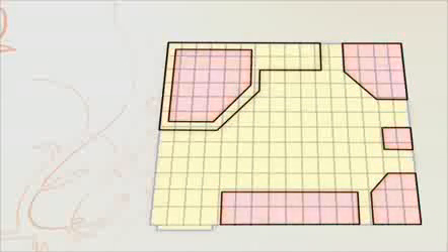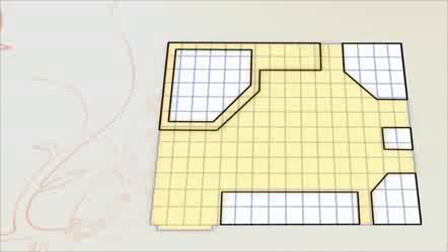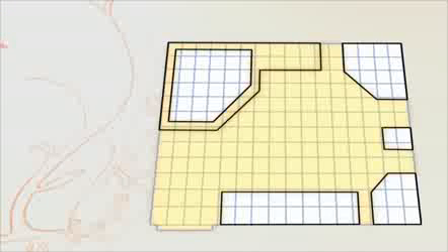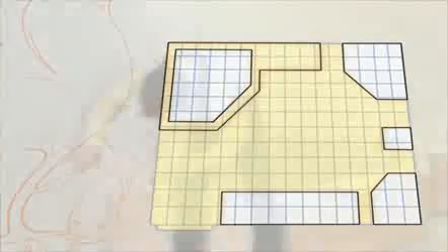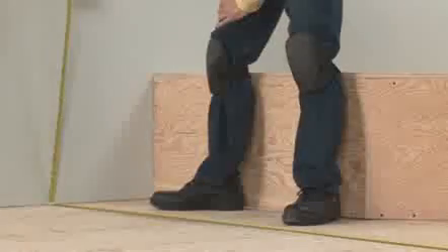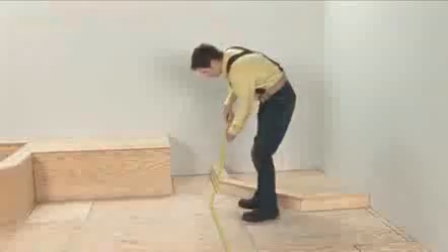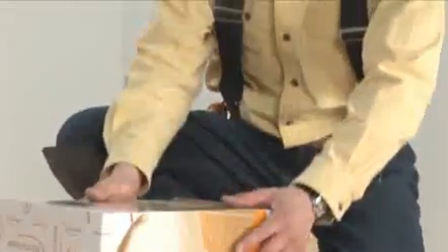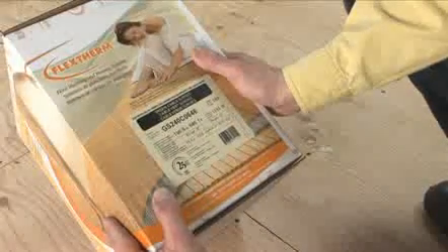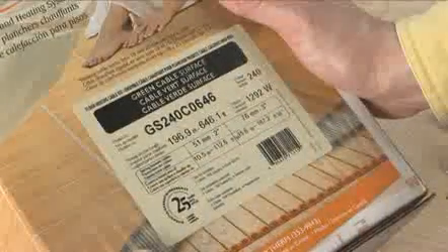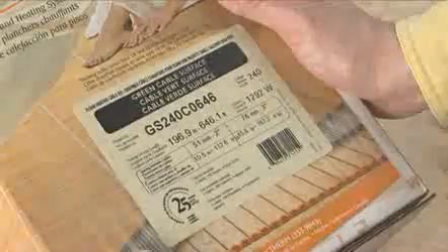Finally, subtract the net area of each obstacle from the total area of the room to arrive at the net area to be heated. Repeat the measurements and calculations to be certain that you have accurately calculated the surface to heat. Check the label on the package to confirm you have the right length of cable for the area to be heated. Never install a cable designed for a larger surface since it cannot be shortened.